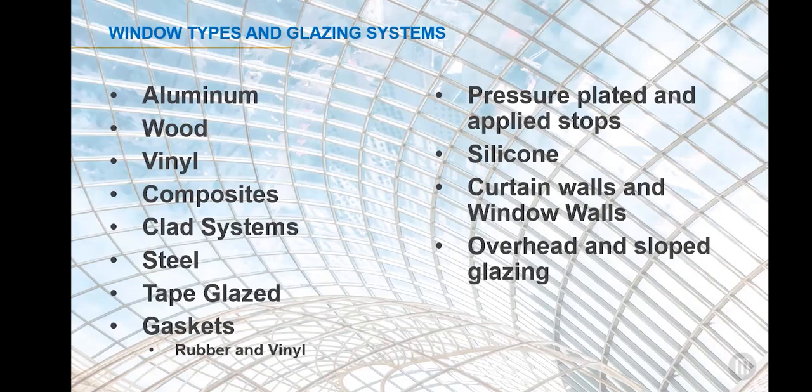Dry glazing is the installation of glass using extruded gaskets in PVC or EPDM to 1 or both sides of the glass to provide a compressed weather seal. No sealants or putties are used in this system, and the windows are designed to be self-draining. In some low exposure conditions, glazing tapes can also be used on the inside.